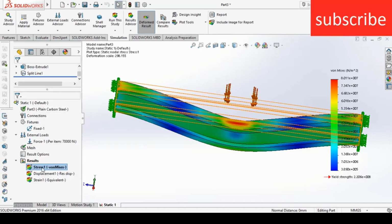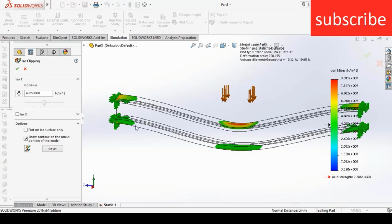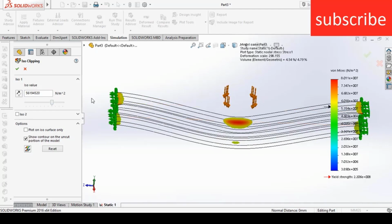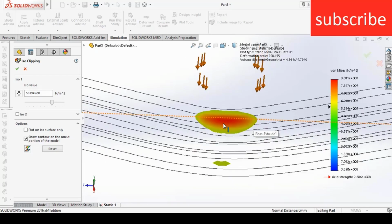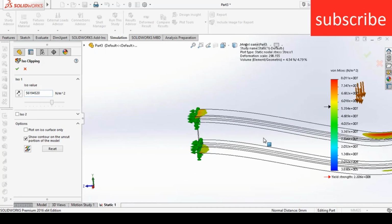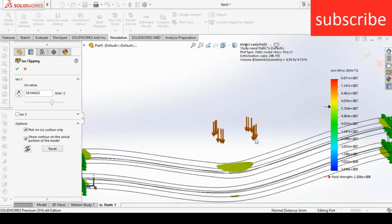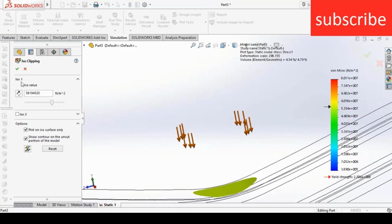Now let's see another thing we can do, ISO clipping. Here you can see it's showing me the values above this value, 4 lakh something. So if you want to show the stress at a particular value, for example you want to know where the stress above this value is acting, you can get a clear picture from here by ISO clipping. It shows where the stress above this value is acting. You can also click plot on ISO surfaces to get a clear picture.